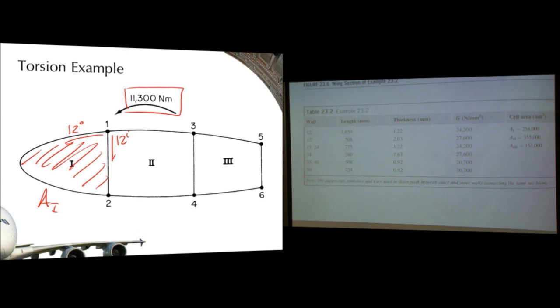So the first thing we generally do with this problem is calculate all our deltas, because our deltas are just going to appear in all of our equations, so getting rid of them early helps us out a lot. Okay. So what we'll calculate is the delta for each wall, and you can do this in the table. So delta is just length over thickness, so you can just add another column in your table for your delta.